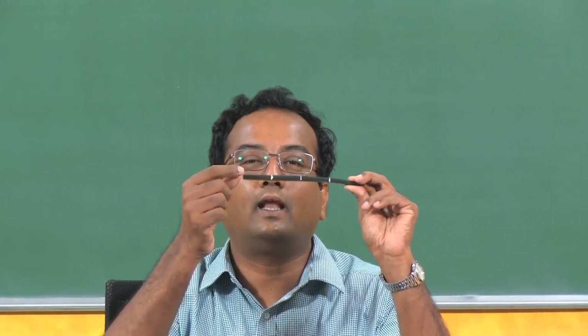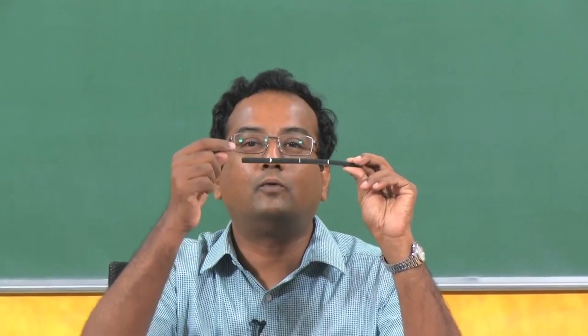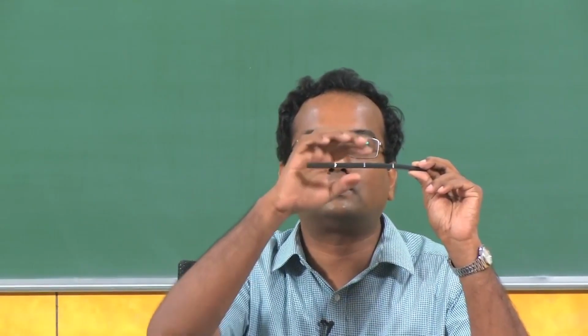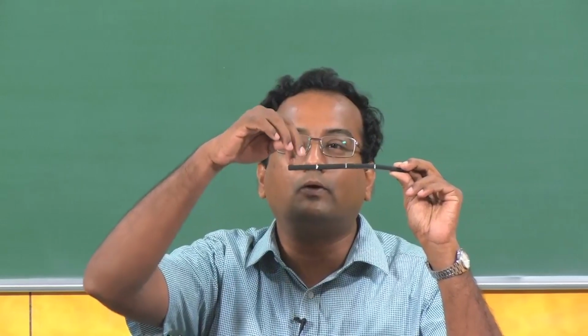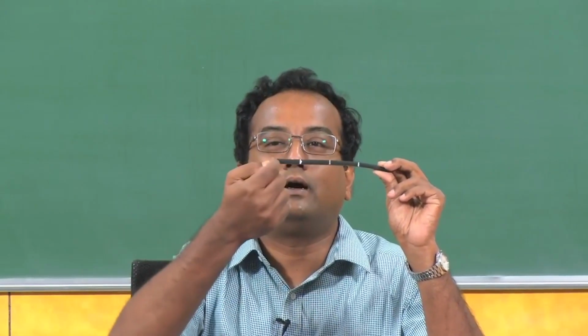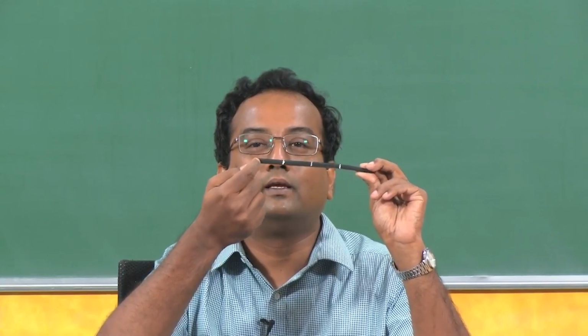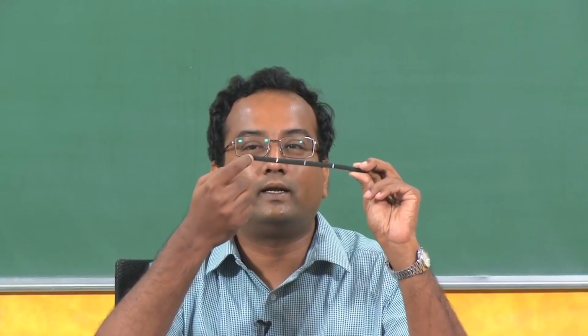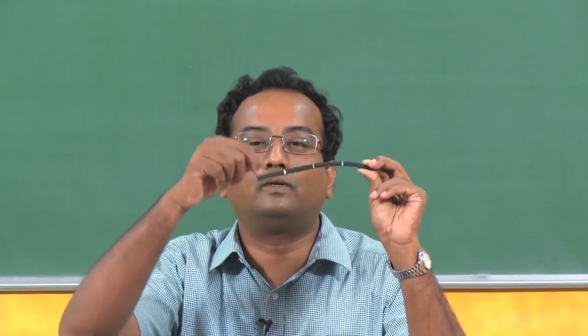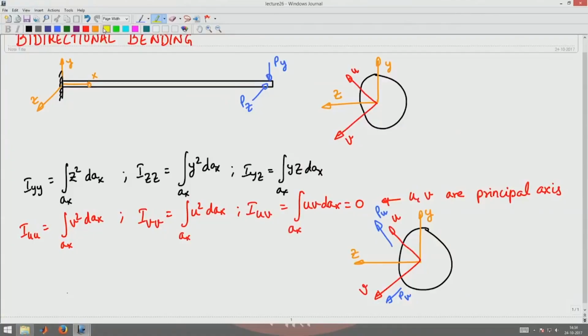So, we are interested in analyzing what the displacement field will be and what stresses will develop in this cross section due to loads applied both vertically and perpendicular to the plane of the beam cross section. We are interested in studying this displacement coupled with this displacement in this lecture. So, now the scenario is one wherein the load is applied along the principal directions, both the principal axes u and v.